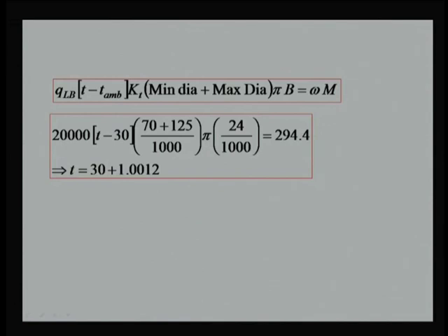We can choose this kind of bearing from a friction point of view. It's not going to cause much loss or much energy loss. It's not going to change the bearing dimension significantly. In this case, a 1 degree temperature rise is tolerable, so we can go ahead with this.